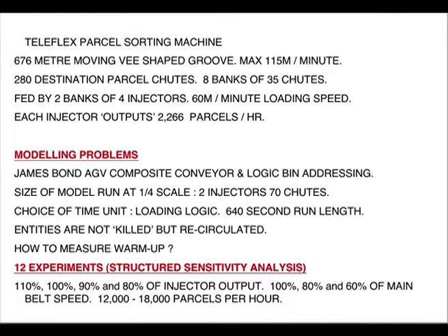Then we come to the choice of time unit, loading logic and 640-second run length. In this case, entities are not killed but recirculated, and the question was how to measure warm-up. Warm-up is when a system starts empty, and the queues in front of the different workstations will be small and parts will go through the system quickly. Such data has to be discarded. Only when the system is warmed up should data be collected.